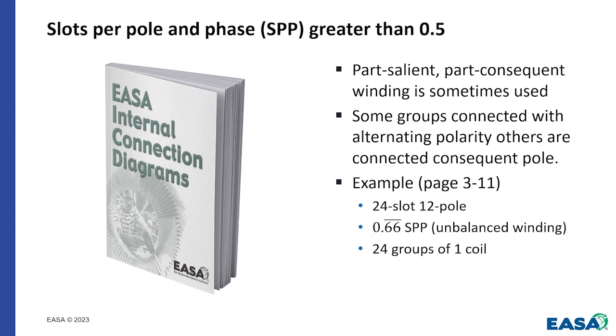So that means that as the EMF is generated, that back voltage, speed voltage is generated back into the winding for the 3 phases, it's not going to be the same like it should be for a balanced 3-phase load. So we're going to have a difference in the voltage that's generated in each phase, or the angle between those voltages not being 120 degrees like it should be, or a combination of the two. So again, this is not the motor you want to really brag about if you're building a one-off. This is something somebody built because of the convenience.